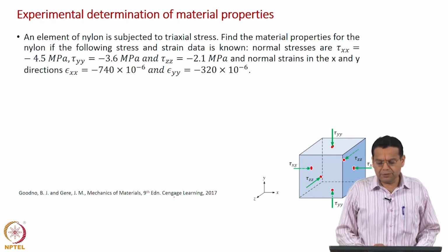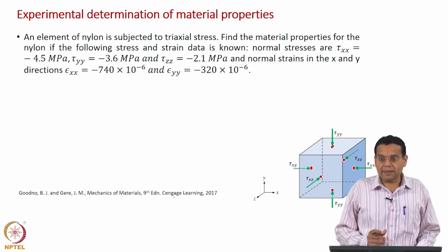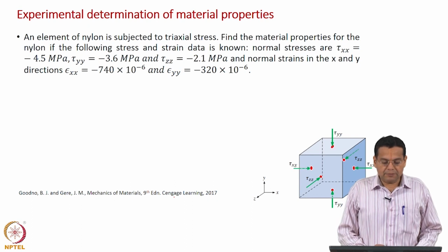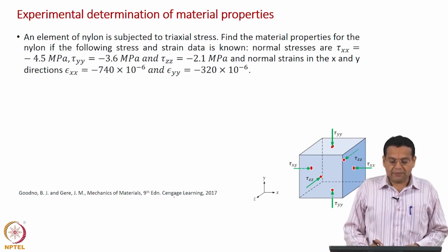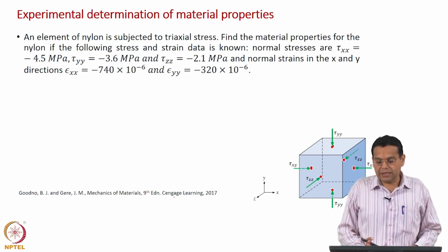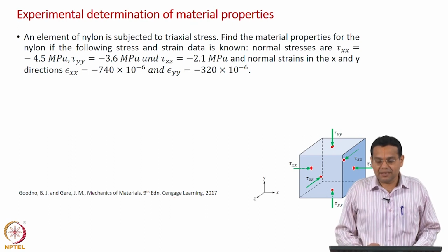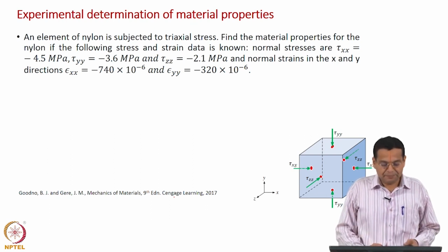In terms of units, the stresses are in megapascal, force per unit area. The strains are dimensionless, so just a number. The values are minus 740 10 power minus 6 and minus 320 10 power minus 6. So, they are small values. We said we are going to analyze under very small strains, and so these numbers cannot be very large.